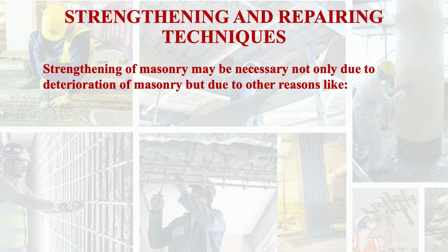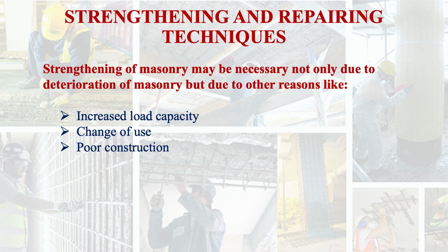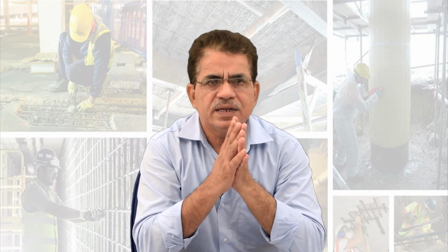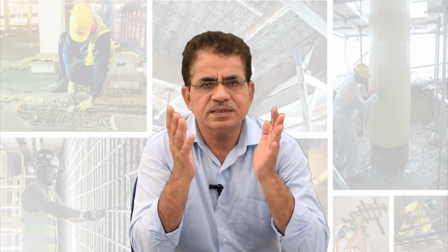Strengthening of masonry may be necessary not only due to deterioration of masonry but due to other reasons also, like increased load capacity, change of use, poor construction, poor design. If these factors are there, then strengthening of masonry is required.